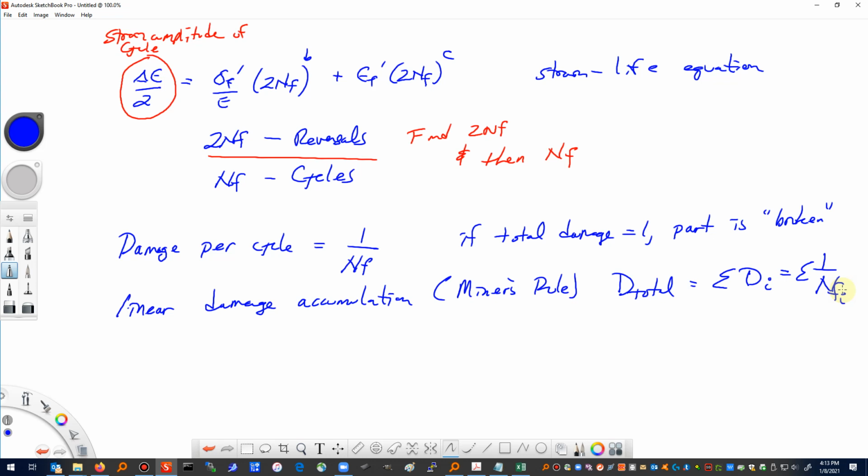So if we go back and look at our pothole history, what we're going to be eventually able to say is for these particular material properties, this vehicle will last 1,000 potholes just like that, or 10,000 potholes just like that, or whatever the number is. We'll be able to calculate what we think that component can sustain before it has cracked and is meeting whatever we define as our definition of failure.